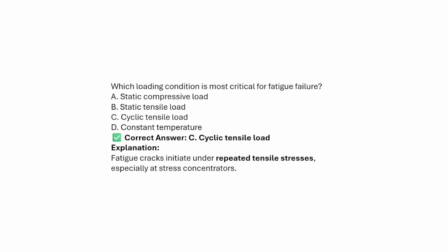Which loading condition is most critical for fatigue failure? Static compressive loading, static tensile loading, cyclic tensile load, and constant temperature. The answer will be cyclic tensile load. Fatigue cracks initiate under repetitive tensile stresses, especially at the stress concentrations.